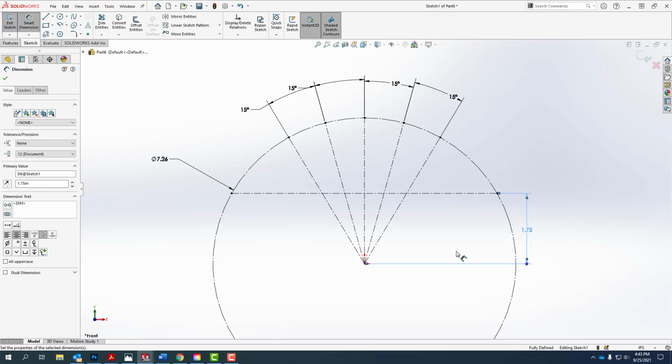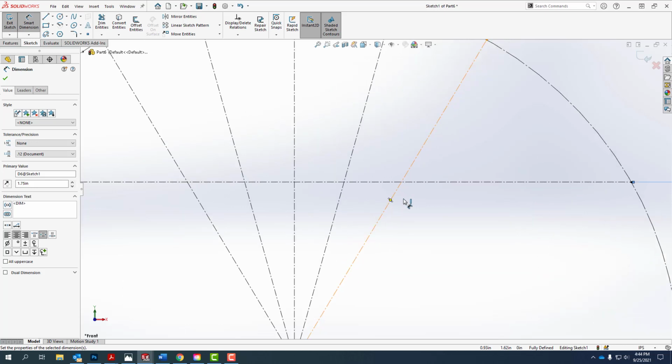Now there's lots of circles here, and the callouts on the circles, there's one that says 7 by radius 0.38, and that indicates basically all the rounded surfaces that make up the outside curve. And the other ones are 4 by radius 19 and 4 by diameter 0.38. These are the next circles that we're going to put in.